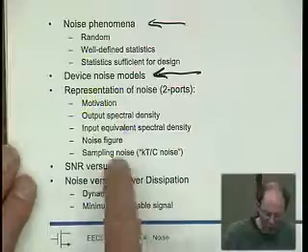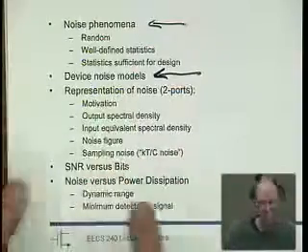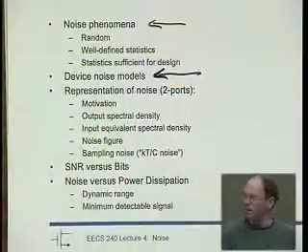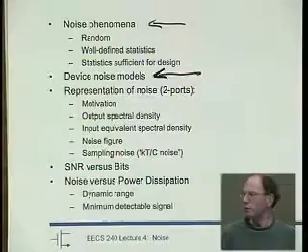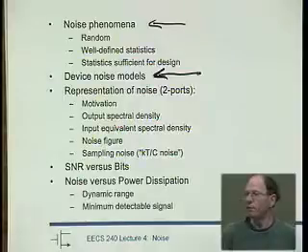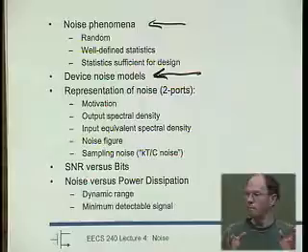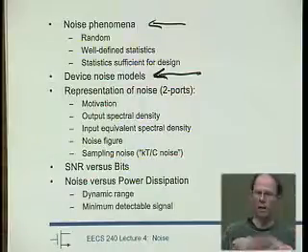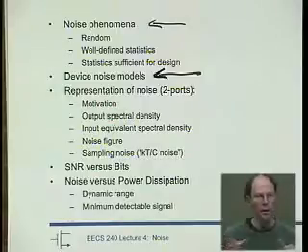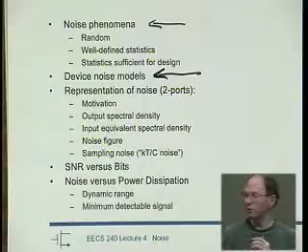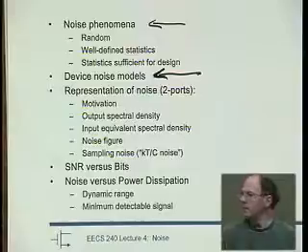And so we're going to talk about a whole slew of ways we can express the noise of a circuit so that it's going to be useful when we're using or specifying this circuit. One common thing that you may have seen is when you look at operational amplifier data sheets. Download one from the web, Maxim or National or ADI, whatnot, right? Then you will see that there is a specification on noise, and it's usually called, the wording may change, input referred noise.